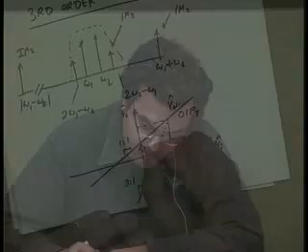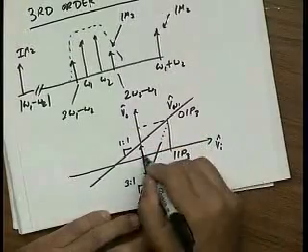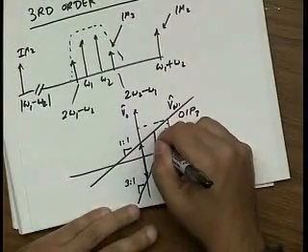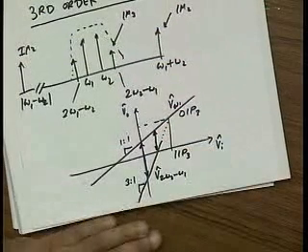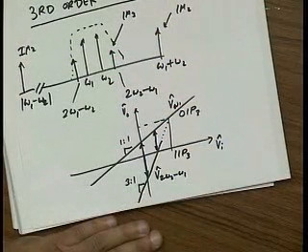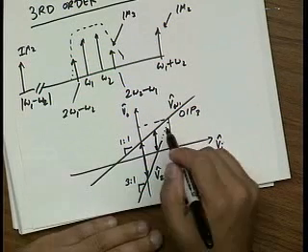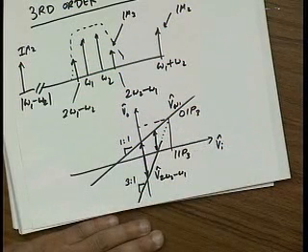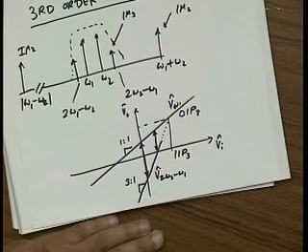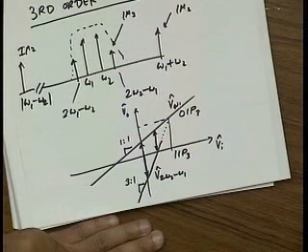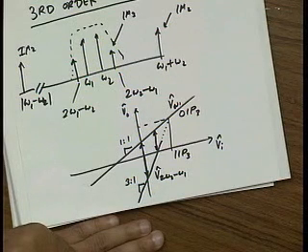So if this is the IM3 at a given input power, if I move over 10 dB, how much does the IM3 decrease? By twice, right? So 20 dB. So if I want 100 dB IM3, I have to back off 50 dB from the IP3 point. So operating at minus 50 dBm would give me 100 dB theoretically of IM3. Okay? Questions?